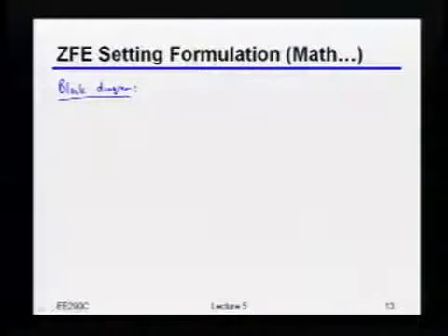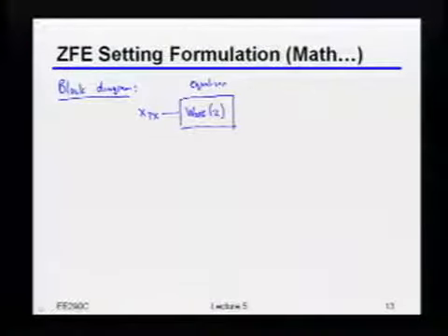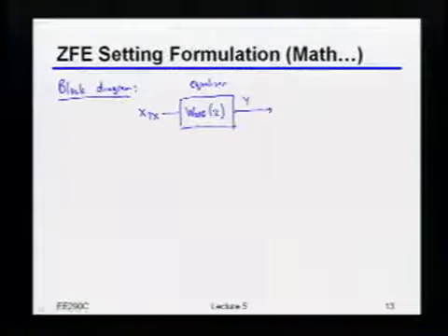Okay, so what we're basically doing is we have some transmitted data bits that I'm going to call x_TX. Okay? What we're then doing is passing them through that FIR filter, which is our equalizer. Okay, and I'm going to call that w_ZFE. Just as a reminder, that's a discrete time equalizer. Coming out of that is going to be some analog but still discrete time quantity, some voltage waveform, which I'm just going to call y_TX.